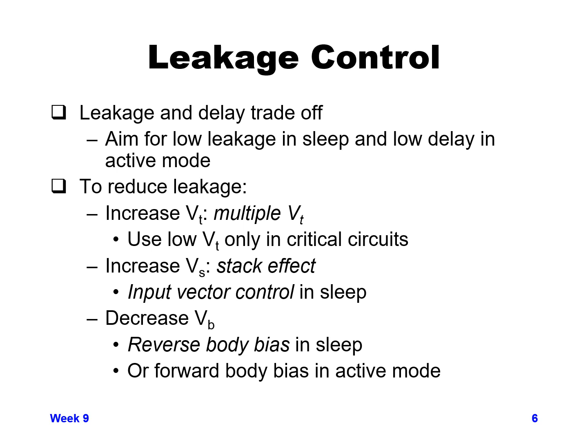And again, you can use the stack effect to potentially have some circuits where you have an extra transistor in series with them. Sometimes this is called a power gate, where you might have a really large transistor or a lot of parallel transistors in series with your power supply going to your logic.